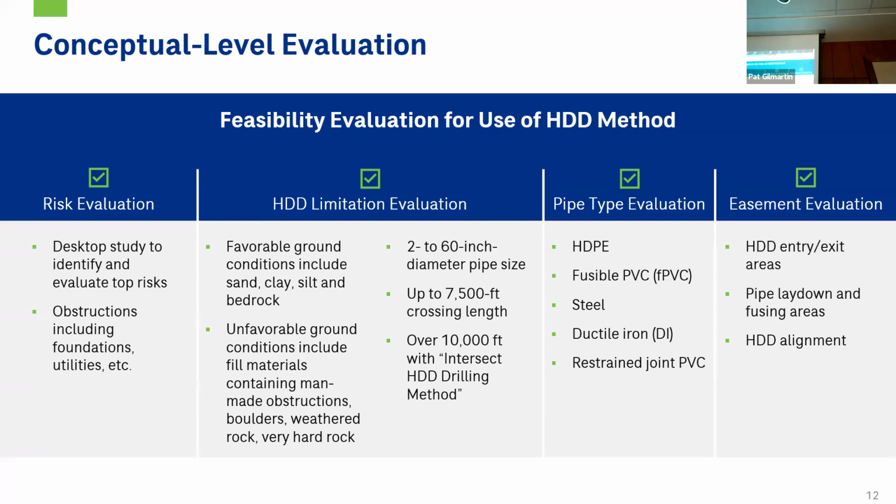In general, for your HDD evaluation, for most soil types and rock types, HDD is favorable. Any sands, clays, silts, and consistent bedrock are all favorable, though obviously with bedrock versus sand and clay, you will have a much slower production rate. Unfavorable ground conditions that you may see is that you have obstructions around here. Obviously, with the partially weathered rock, you can get floating boulders and things like that. So you do need to take those into consideration for your HDD design.